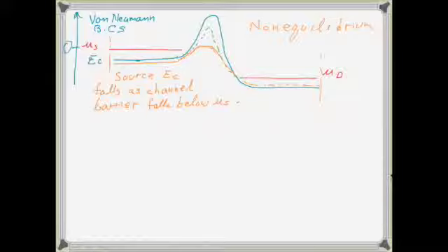Poisson's solution is enforcing charge neutrality in the leads, so the charge is not increasing, and yet the conduction band is falling. How can that be? It seems like a contradiction. In all cases, N is remaining at your doping density in the source.